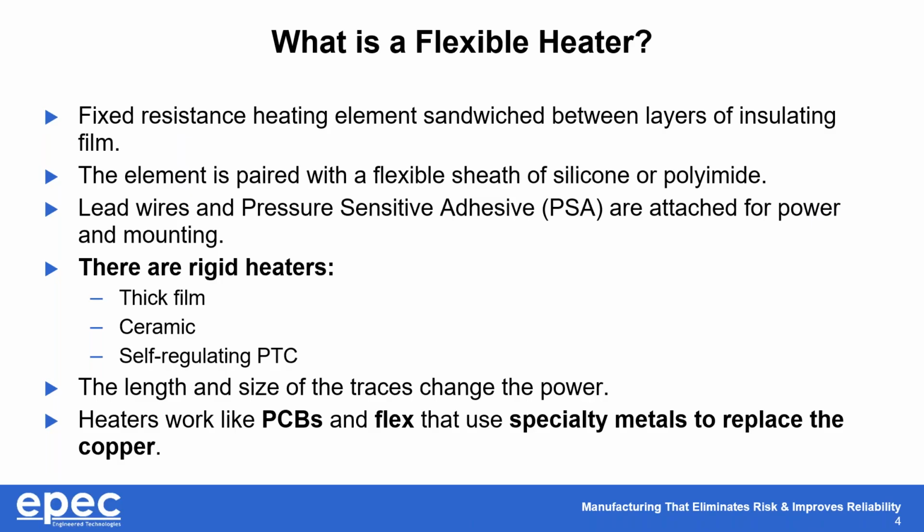Once the heater is actually built, then we need to develop a way to attach power and wires to it, and then a pressure-sensitive adhesive or another way to fix the heater to whatever surface or substrate you're mounting it to. Now, while today's presentation focuses solely on flexible heaters, Epec does support other heater technologies, including some rigid heaters that include thick film, ceramic, and PTC style.